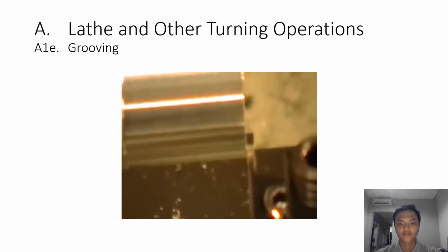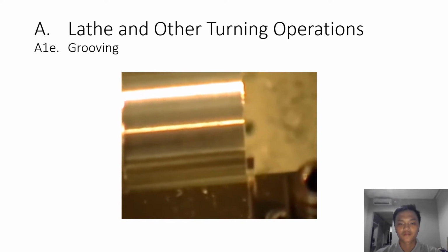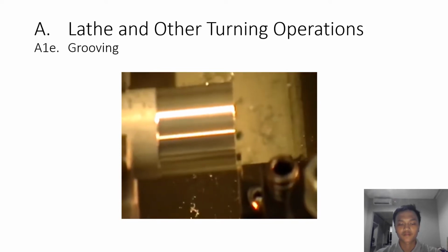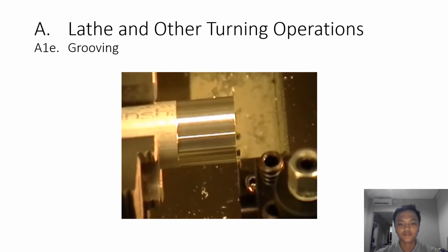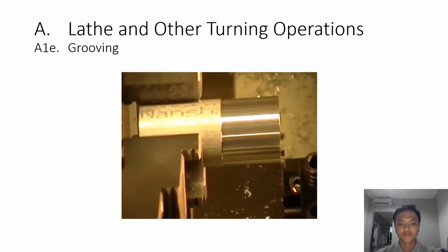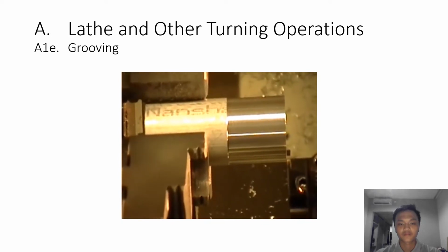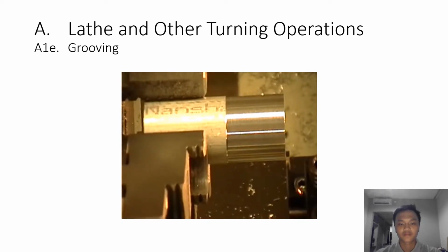Sorry for the jumpiness there. Alright, right at the edge of the part. A little blurry, but you can see where we are. Alright, now I want to position the tool for cutting. I'll cut a groove. Pull this back so I don't smash the tool into the diameter.